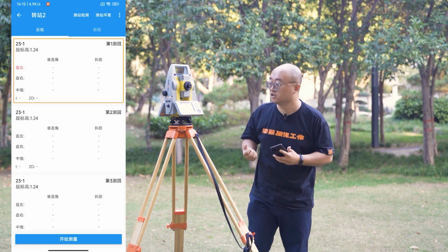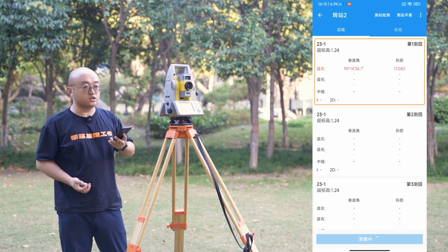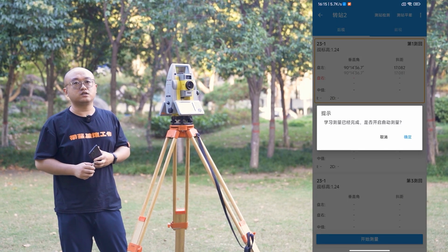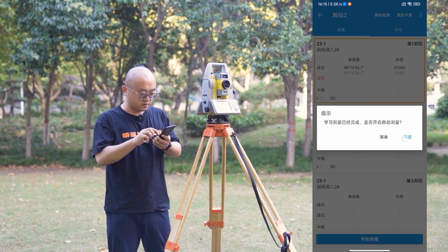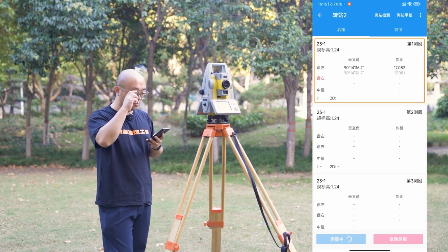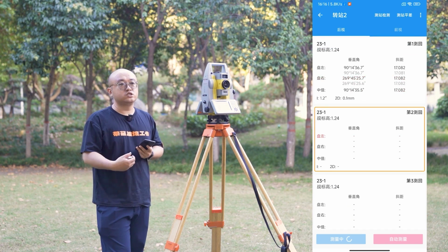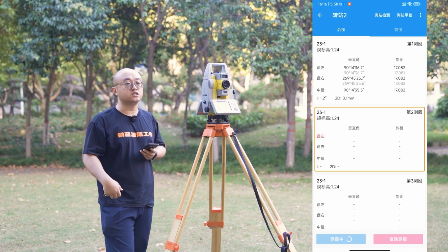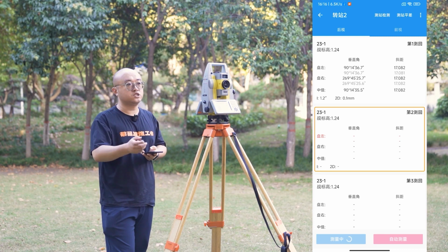At present, the software defaults to 4 measurement sets, as according to the national 3rd and 4th level standards, there is no clear quantity for this measurement set, so we follow the default. Start measuring the first target. Observation is relatively simple. Just aim at one target and observe its 4 measurement values. If you are observing manually, you can also separate it and observe it first, then look forward, and then look back and then look forward, one by one. Alternatively, you can first observe all the backside measurements.